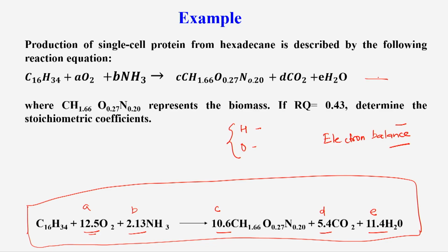What we require for material balance is the stoichiometric relation as well as a flow diagram, and once these two things are there, we can apply the mass balance. But for the stoichiometric reactions, we have to write these equations. Then we have to calculate the stoichiometric coefficients that give the clear relation between substrate and product.